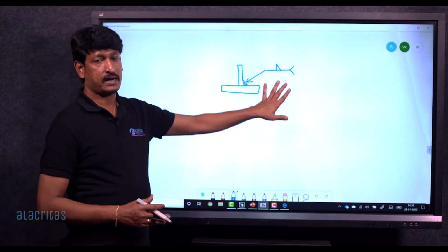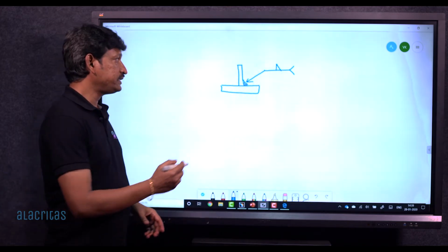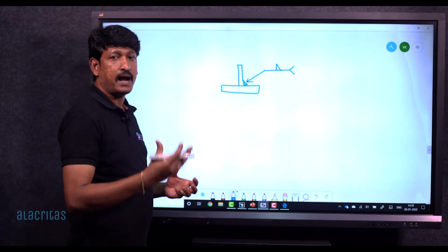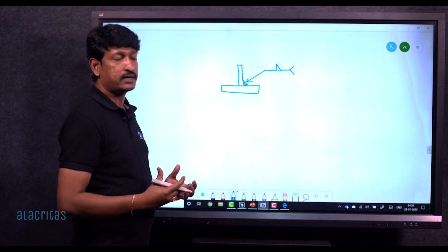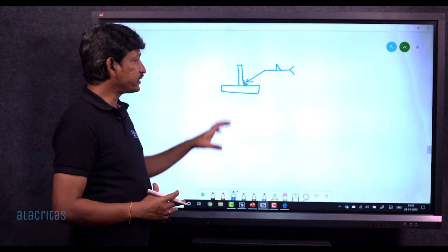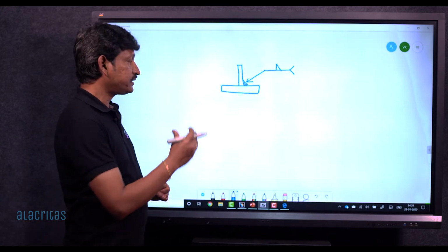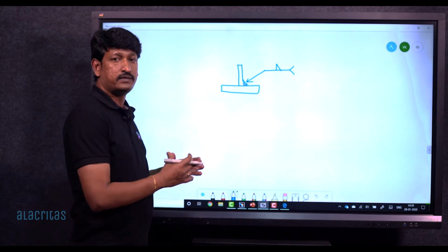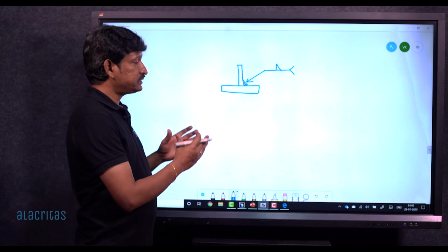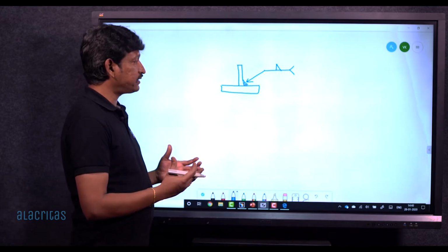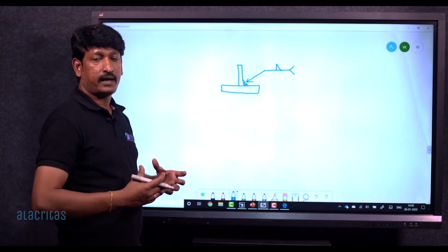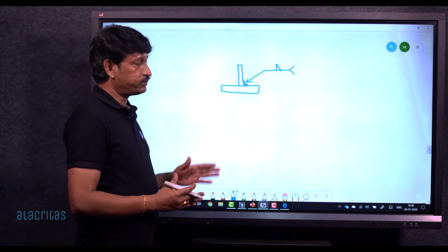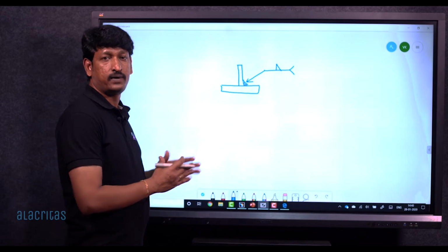This information we can represent in the drawing, but what the weld material is and what weight of weld is added to the product, we cannot know from the drawing. So it is good to have a 3D representation in the software, and we can measure the nominal weight, the approximate weight. We cannot measure the actual weight, but at least we can calculate the nominal value with this weld design.